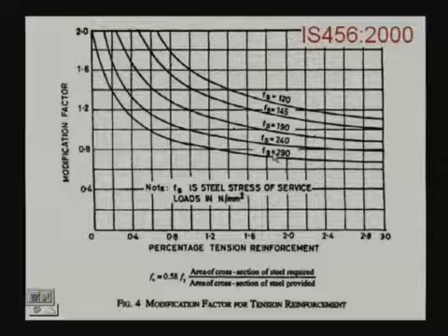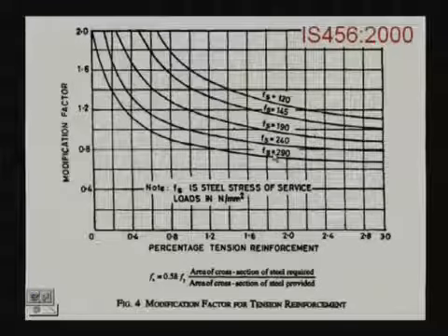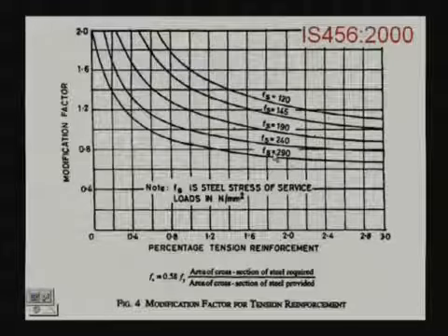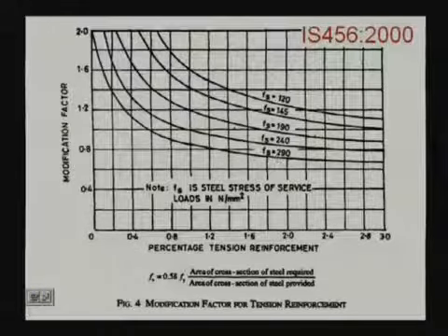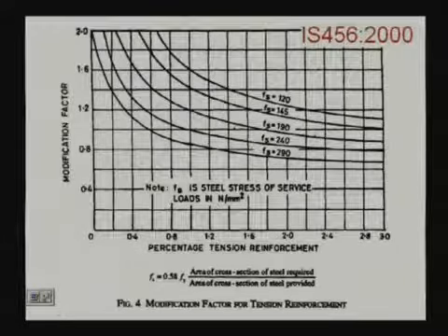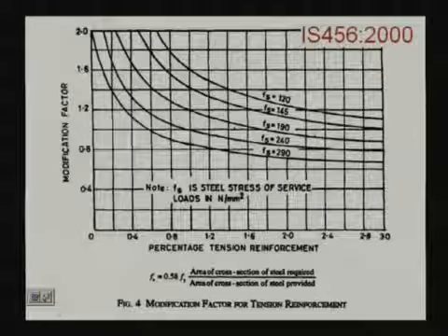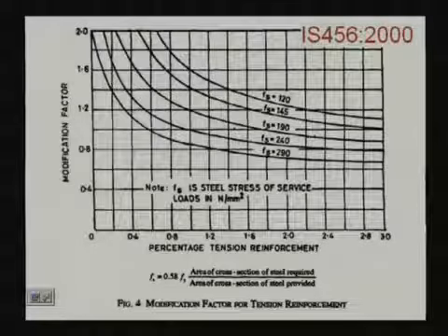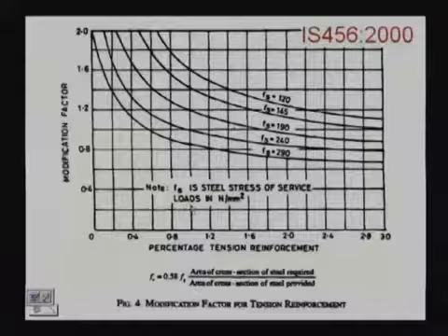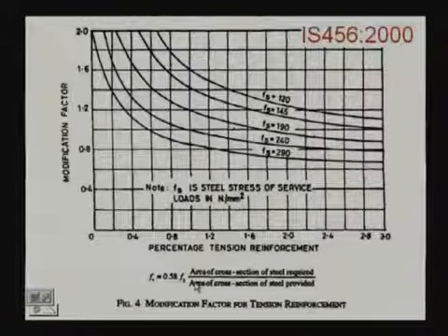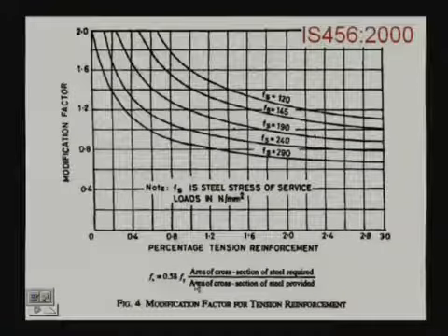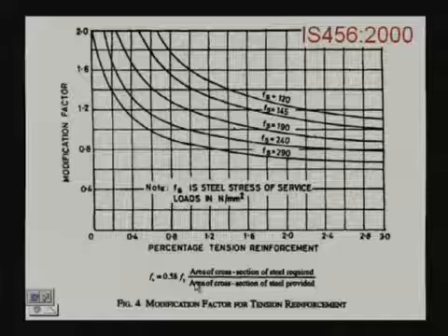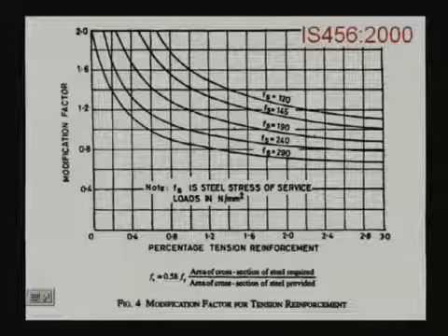Now, how do I know that initially if we start with, say, a simply supported beam, 20? Here we have to modify the value, but how do I know? That means it will come from our experience, what percent of steel we generally use for slabs. On the basis of that we can find out a certain factor, or in another way we have to redesign it. We start with the basic value, then do the whole process again, but we generally do not do that, because if we are experienced, then on the very first trial itself we can go.